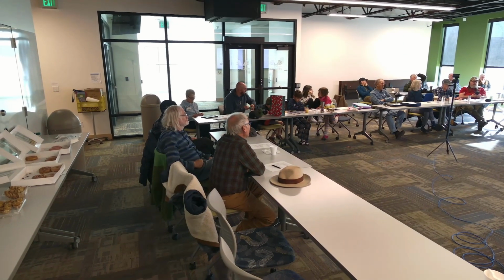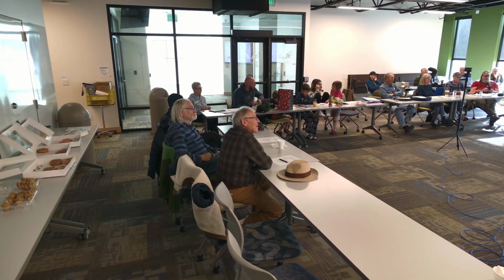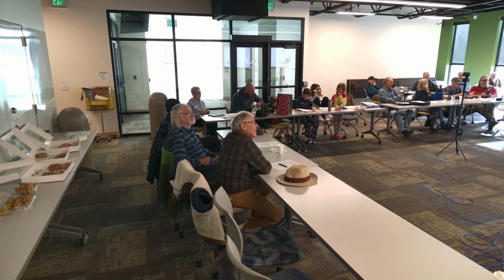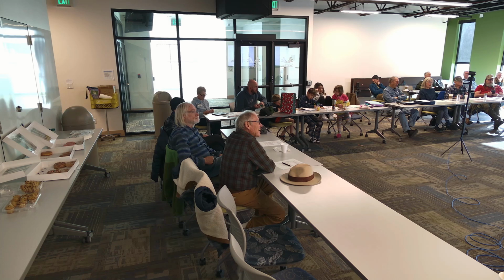What's the lifespan of one of those high dollar bits? You can burn a bit up in a day. Yep. So most of the time, if you're doing the right drilling performance and babying the bit and actually doing what it should do, it'll last you a good week. And you can drill like that without ruining the bit. So they'll bring the bit back out, and then they'll just replace those cutters, as we call them, on the top of the bit. And that's the cheapest way to do it.